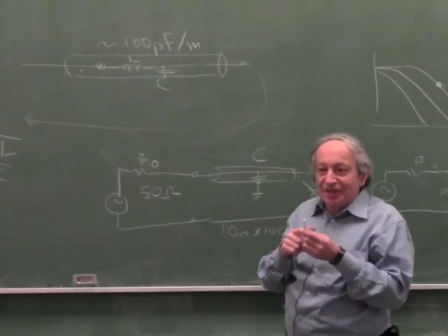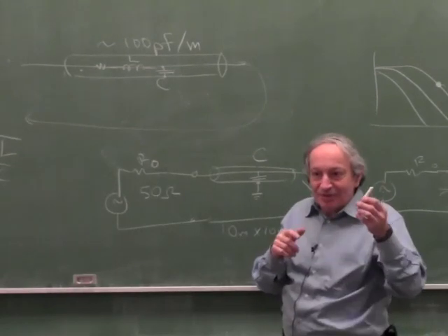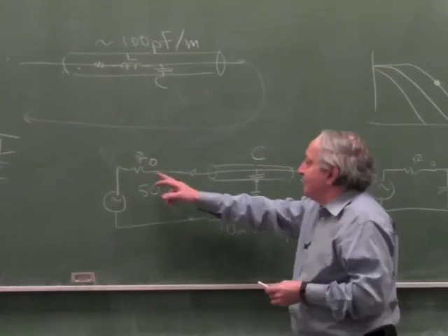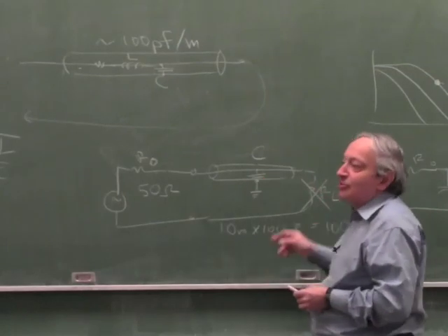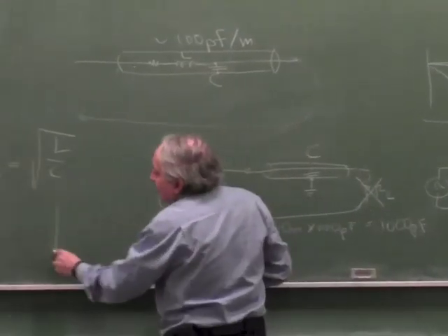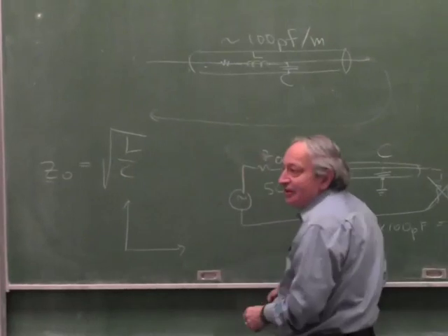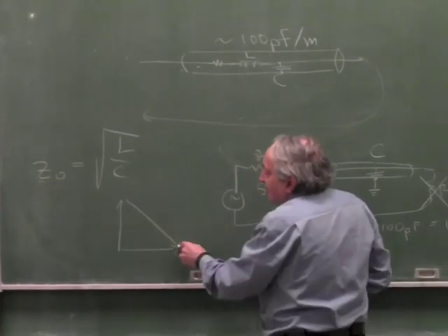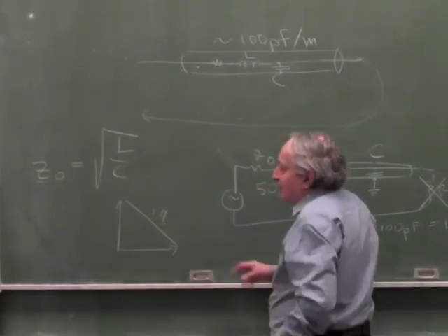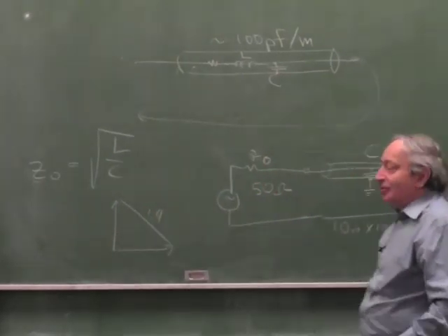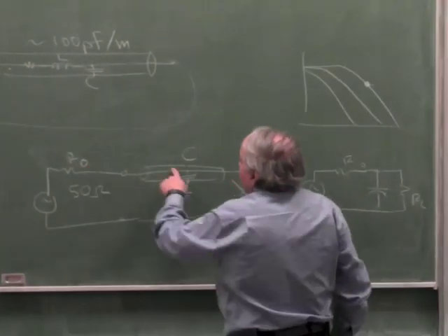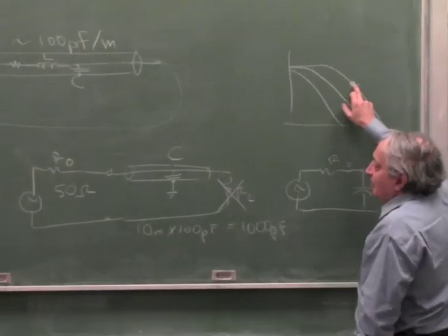There are two vectors at 90 degrees out of phase, right? You remember that from somewhere. So when the two impedances are equal, the voltage only drops to 0.7, because when you take two vectors and they're equal, this vector is only 1.4 times this, not 2. So when this equals this, the voltage drops to 0.7, which is the 3 dB point.